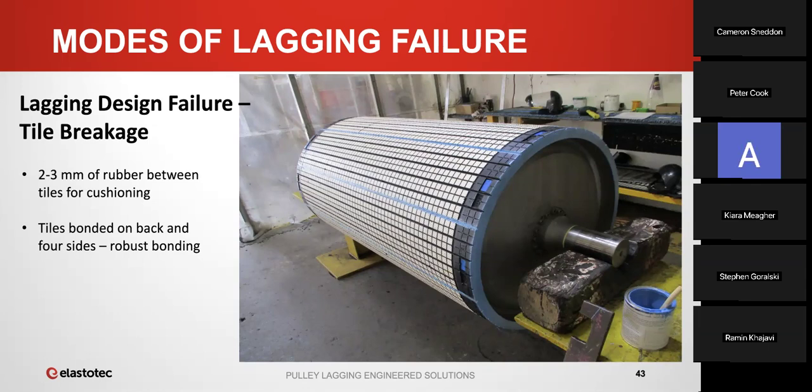There's no cushioning, and ceramic is inherently brittle, so you just increase the likelihood that those point loads will actually fracture the tiles. The thinking behind putting 2 to 3 mil of rubber between each tile is that it provides some cushioning from those point loads, and it helps to reduce the chance of breakage.